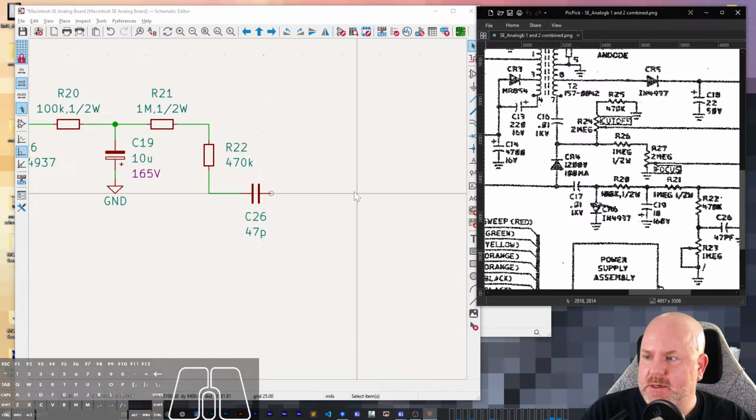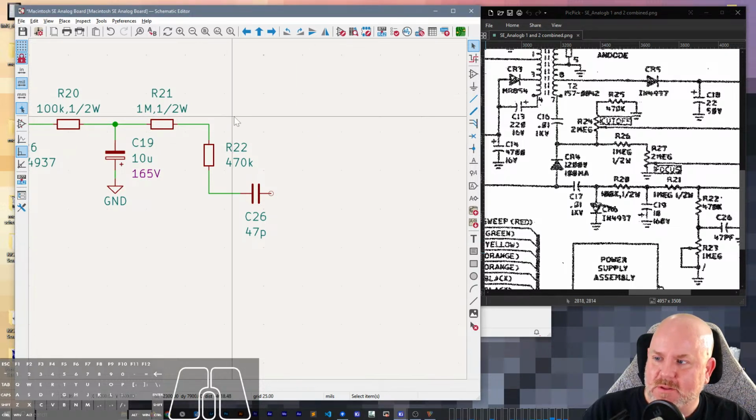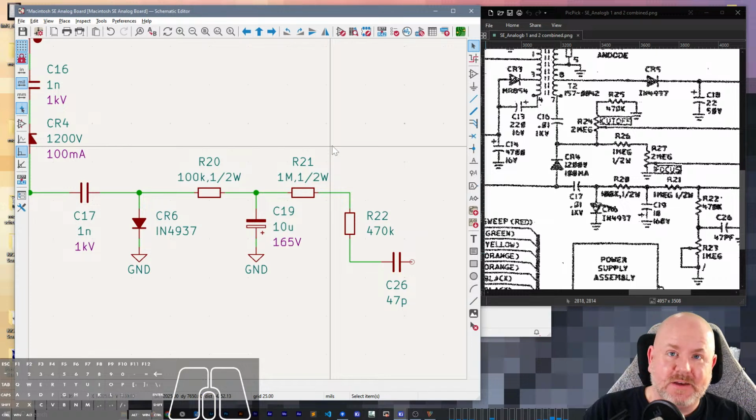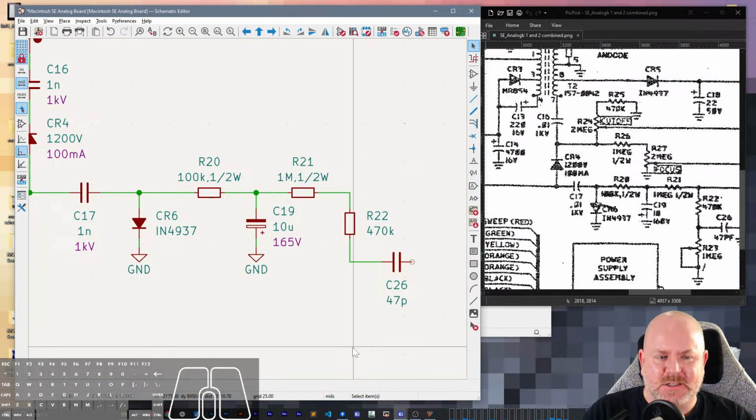I just saw that. Squire, what are my tips? I'm backing up. My thoughts on low temp bismuth solder. I actually have a Workbench Wednesdays video on low temp solder, in which I cover bismuth. I like the bismuth-based solder. I do not like the indium-based solder, which I think is the other low temp compound. It just doesn't seem to work as well for me for a variety of reasons.